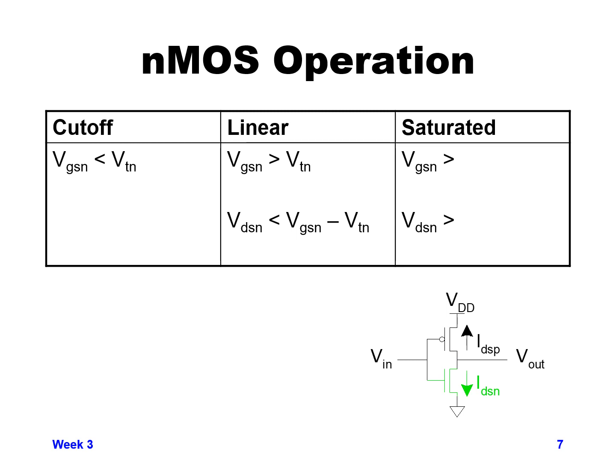And then of course the saturation region: your VGS again is greater than the threshold voltage, and your drain to source voltage is greater than VGS minus VT, and that's when you're in the saturation region. So let's put this in terms of Vin and Vout instead of VGS and VDS.